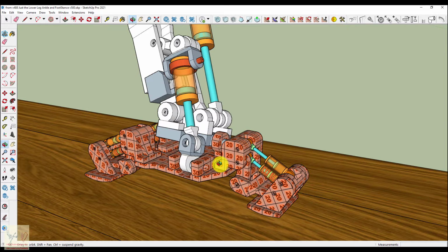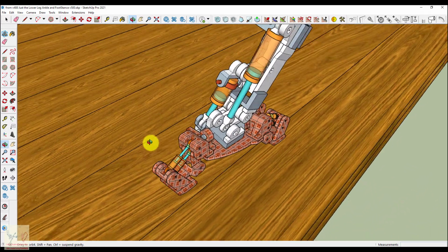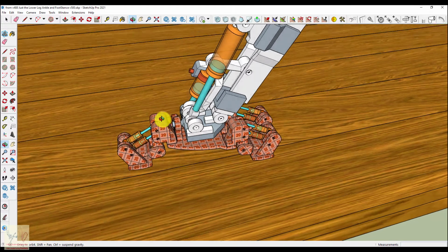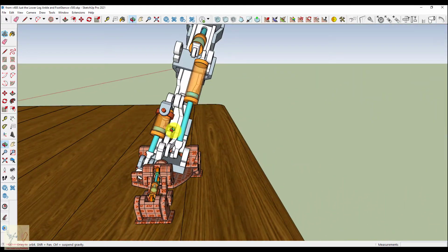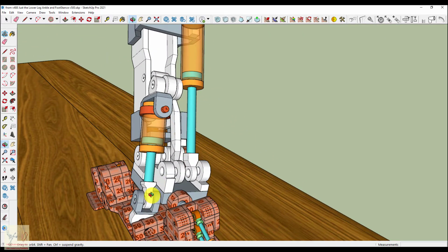And you would have to have a program adjusted so that whatever that dorsiflexion, plantar flexion command did to inversion and eversion, the inversion and eversion piston would have to receive a set of commands to undo that, which is complex. And it could be that you can get out to where you're outside of the range of what this piston can do.